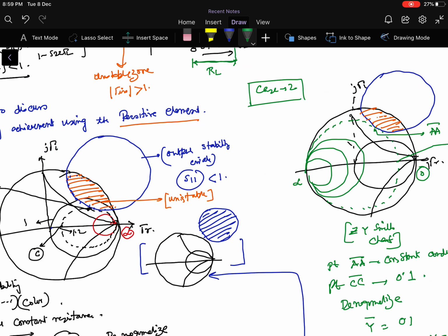We do all this so that we can drive the output or input stability circle away from the Smith chart, and we do not get any intersected region, so that we can access our total load freely and don't have to bother about stability. That way we can make the transistors unconditionally stable from the potentially unstable case. I have done this for the output side, because I took all the values from the output stability circle.